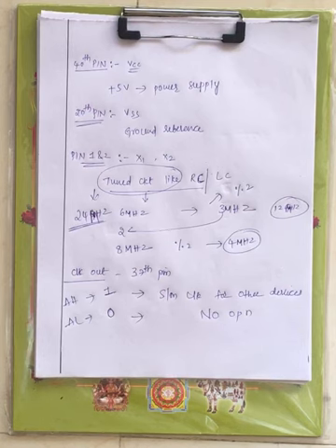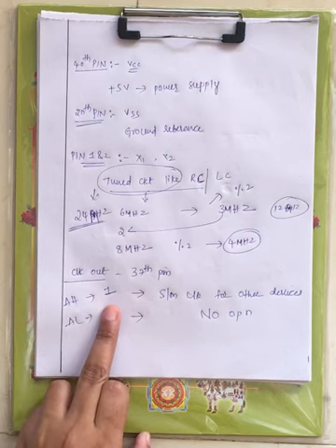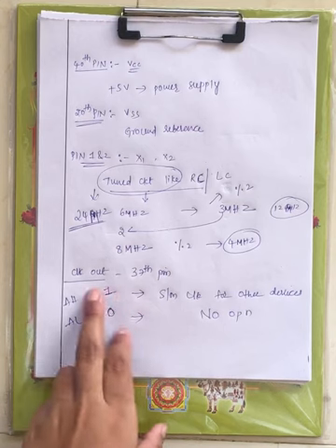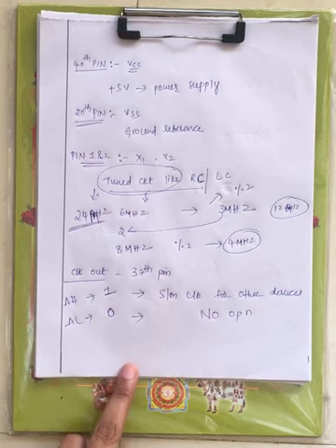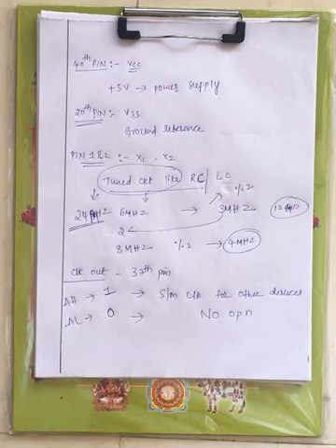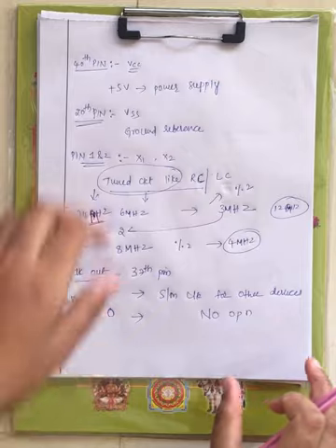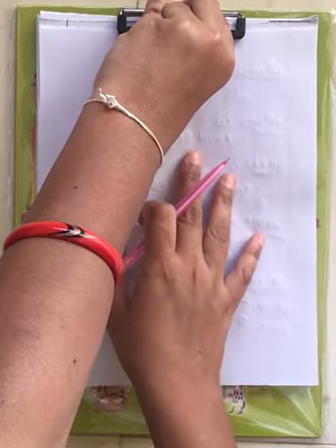When it is active high, that is 1, this signal can be used as a system clock for other devices. When it is active low, which indicates 0, you can't use this signal as a system clock for other devices. These are the power supply and clock signals of the 8085 microprocessor.